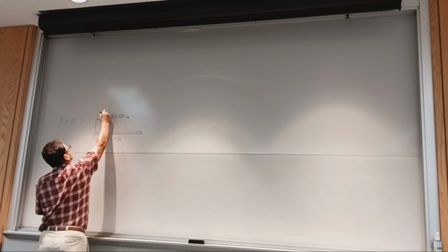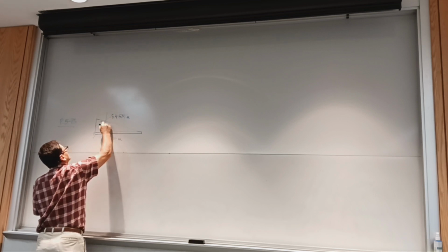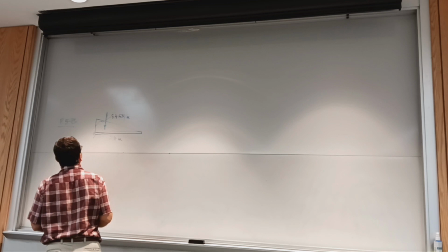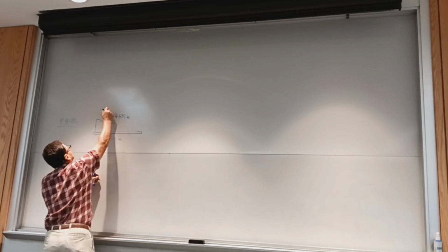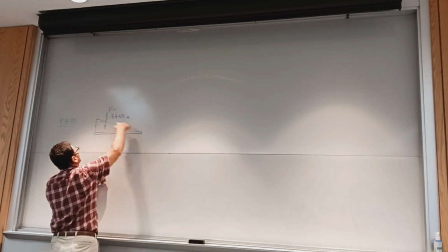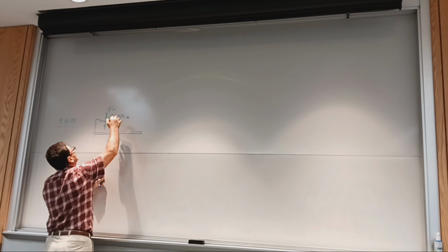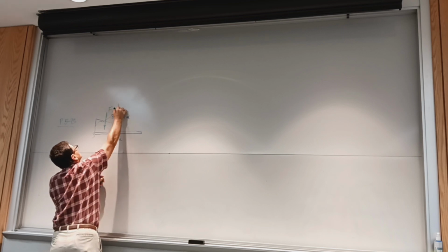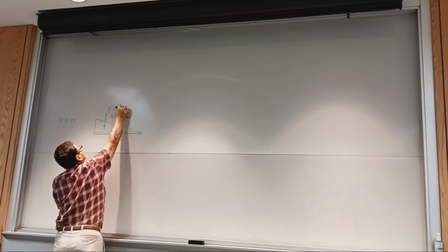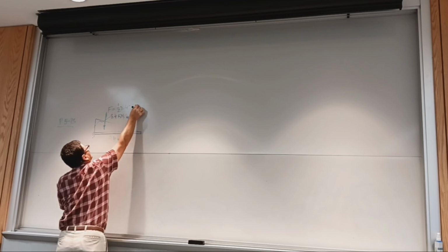And so we have a distributed force whose equivalent is a concentrated force equal to this area. Again, they don't act simultaneously. So this force F is going to be the area of a triangle, 1 over 2 times 8.4 multiplied by 2.4.